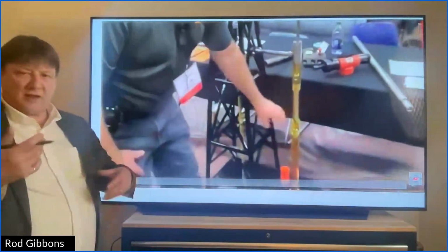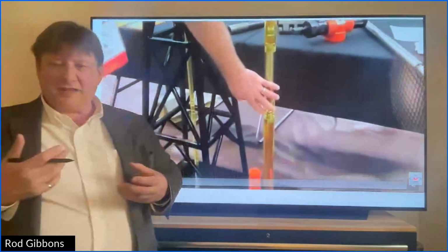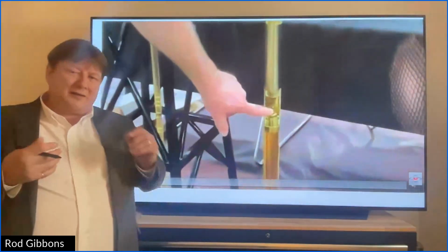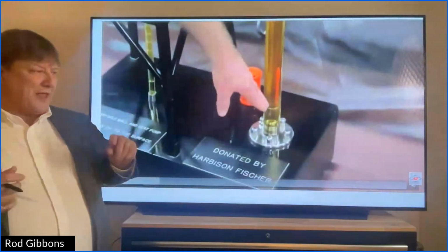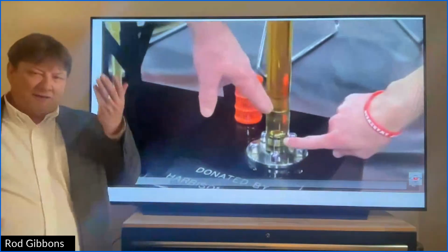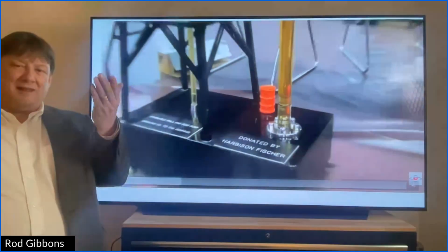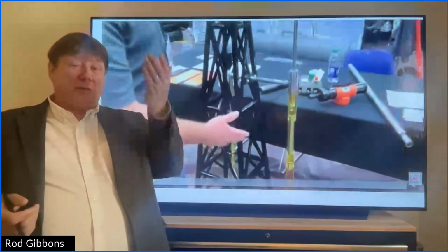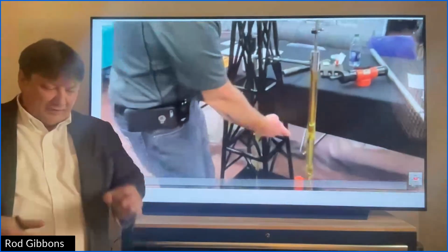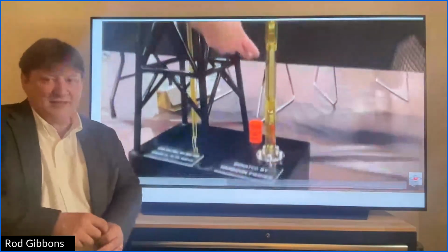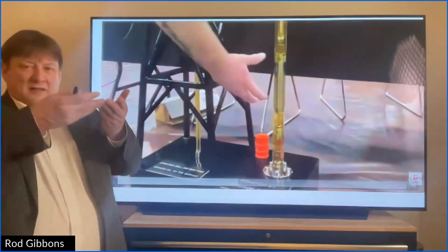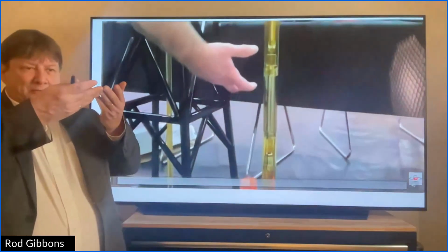And that cycle just continues. It's just those two balls. Again, when you see that pump jack going, the donkey's head going up in the air, it's on the upstroke, and that traveling valve is sitting on its seat and it's lifting the oil out of the well.